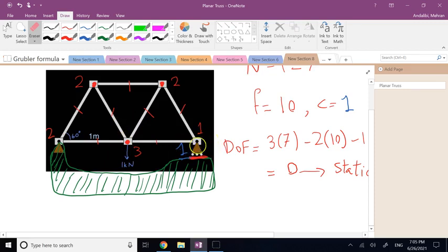Okay, so by allowing this motion, you're trying to reduce the amount of stress, tension, or compression in the members. Okay, because if you fix this side, then this point cannot move at all. And then if there is even no physical load, but just like thermal load, that will also cause thermal stress, which then can be added to your physical stress due to the loads, physical loads, and that will bump up the total stress in the members and break them faster.